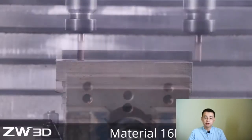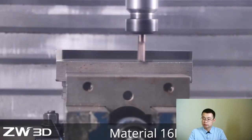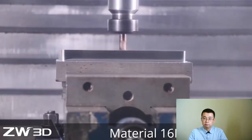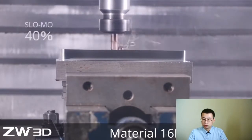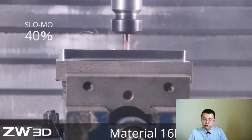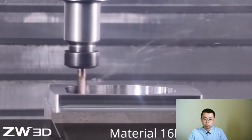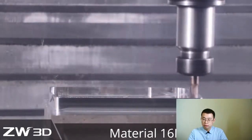Okay, the cutting begins, and this is the first cut on the side. You can see that almost the full length of the tool is being used. In this way, it will cut deeper and faster. Let's slow down when it is cutting into the pocket, and you can see that it cuts very deep. And in the following cut, you can check the way volume mill will move the tool. It will always try to use as much length as possible.